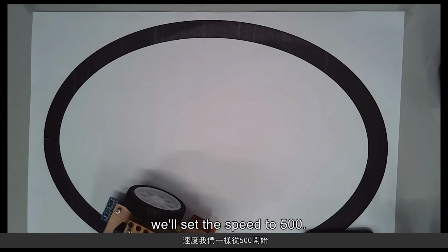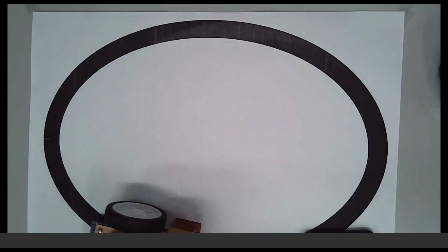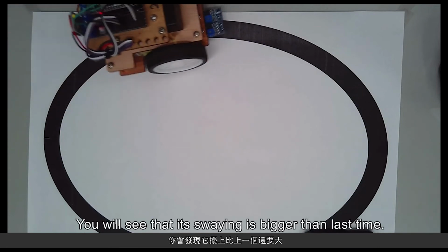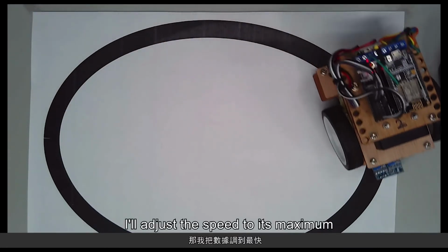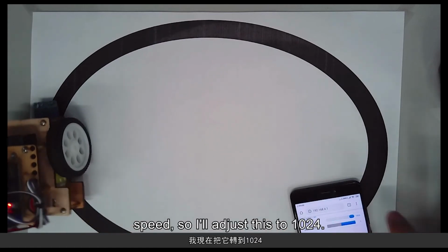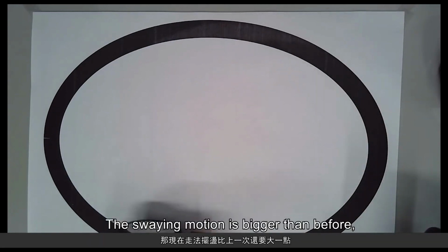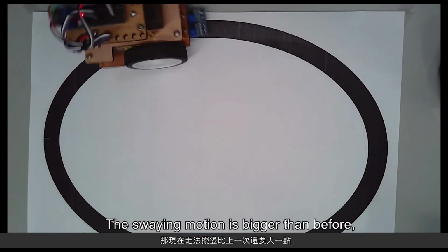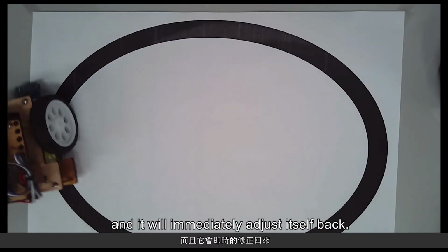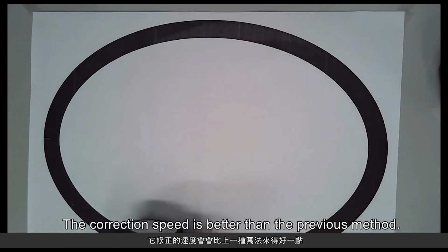We'll set the speed to 500. We'll increase the speed. You'll see that the swing is bigger than last time. I will adjust the speed to its maximum. Because it lost control at its maximum speed, I will adjust this to 1024. The swaying motion is bigger than before, but its deviation from the black area is smaller, and it will immediately adjust itself back. The correction speed is better than the previous method.